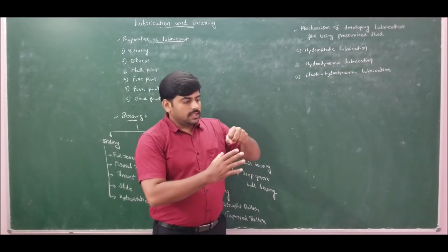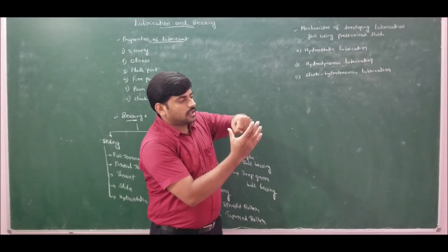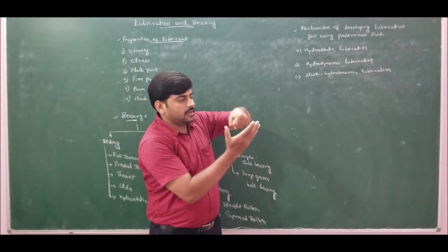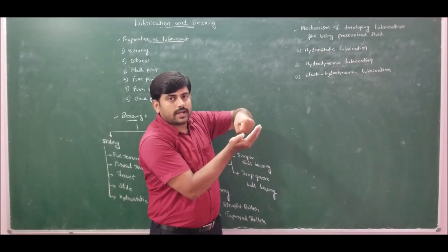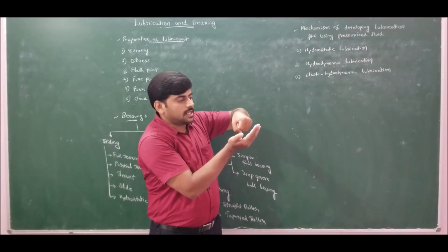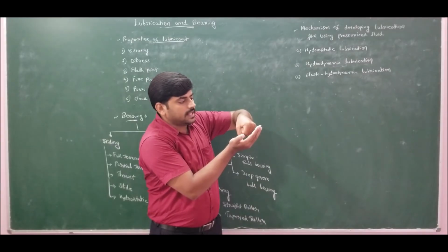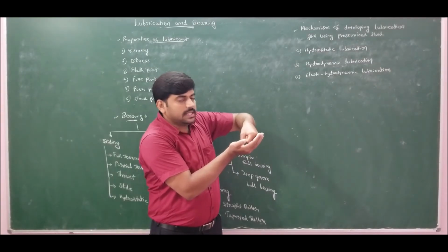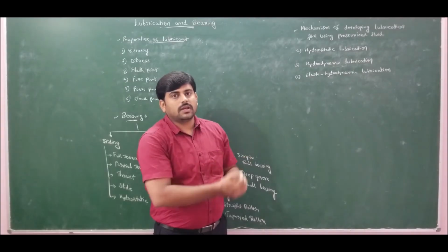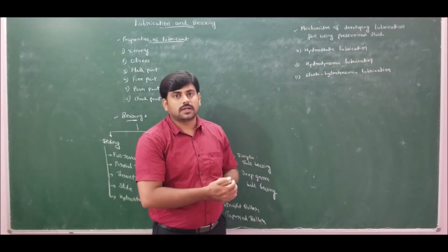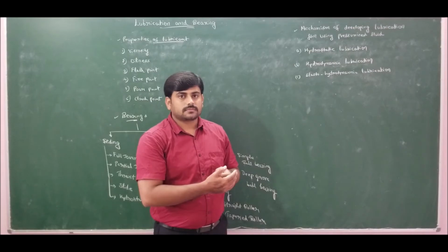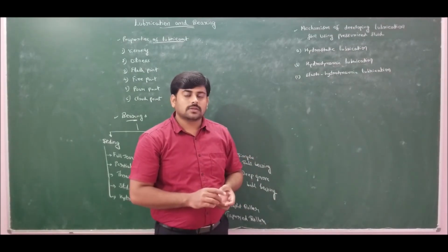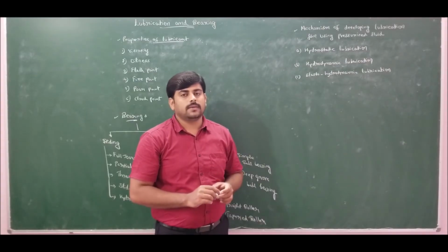Once the journal starts rotating, as it rotates, it starts moving towards the center, and there will be enough gap between the bearing surface and the journal. A thin film of lubrication is provided. If you want to stop the journal, then at low speeds the journal will move eccentrically, and as it slows down, it will come in contact with the surface of the bearing, and it causes friction and heat generation. This is known as boundary lubrication. If a thin film of lubrication is provided, then it is called stable lubrication. Hydrodynamic lubrication will cause boundary lubrication during starting and stopping of the journal.